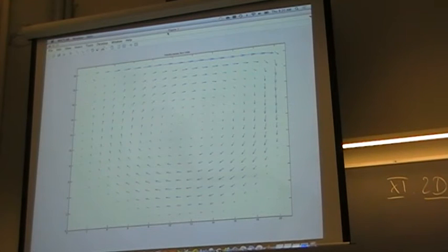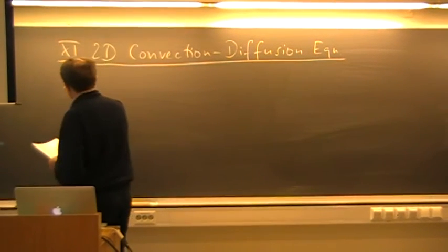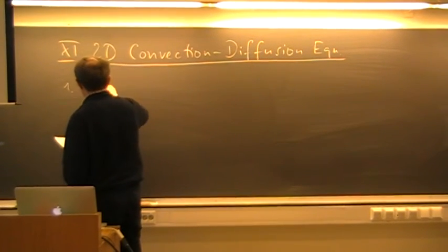So that is something that you are going to play around with, and also to do some other visualization with that. For example, the vorticity, and you have the classical paper by Ghia et al., which Radar supplied, where you can compare your results with those from literature. So that is an example of solution of the convection-diffusion equation inside solving the Navier-Stokes equations, because the momentum equations are, in fact, convection-diffusion equations. So, therefore we start with this, and as usual, we start with a physical and mathematical classification.